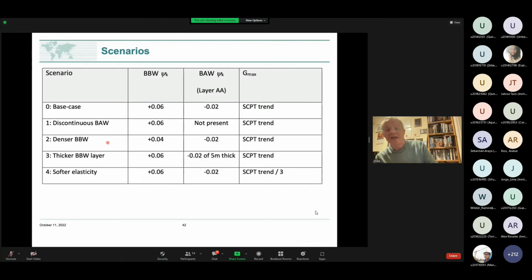With a case history, you really do need to go with best estimates, so we're saying perhaps our procedures have a conservative bias in them. So we said, let's go with something a little bit better. So that became the denser thing. We also said, let's consider the beach below water layer was thicker. Perhaps what we've done from the 2012 CPTs, which only suggested about a 2 meter thick layer, maybe back in 1975, the guys were telling the truth and it was thicker. So we made it 5 meters thick, just to see what the effect would be.